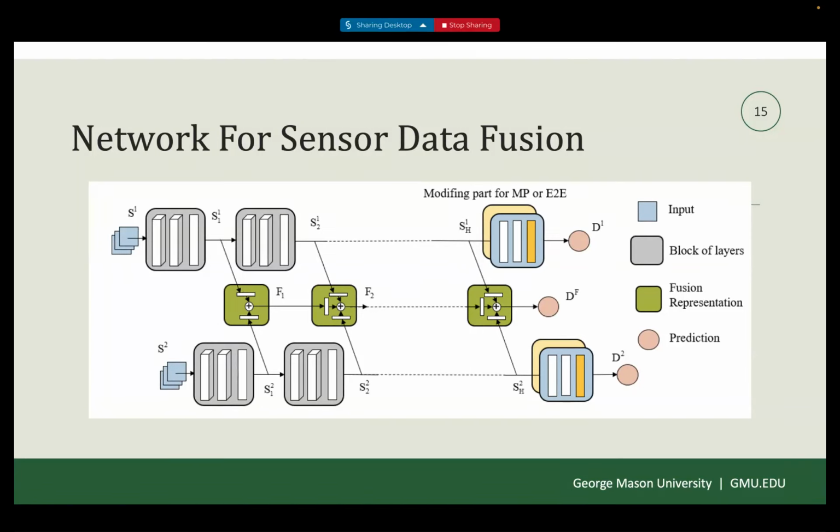And the middle layer is another neural network, which takes the intermediate feature representations of these 2 LiDAR and image networks, and fuses them into a shared space, right? Then all of them are trying to predict the same linear and angular velocities, and the losses are combined. I have not added the maths, but the losses are combined, and then all of the networks will be trained jointly on the same task, right? So this is a high-level overview of the neural network architecture that we are using.